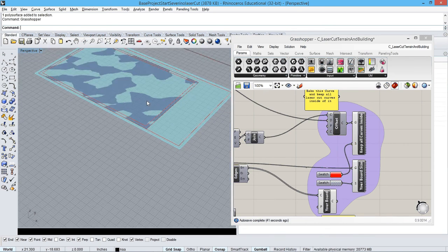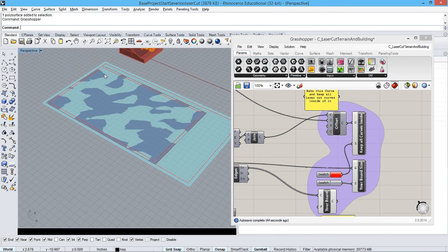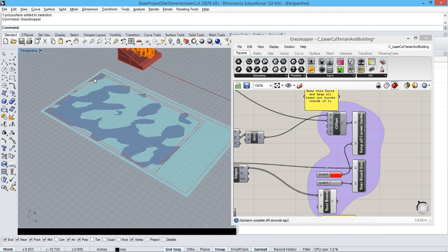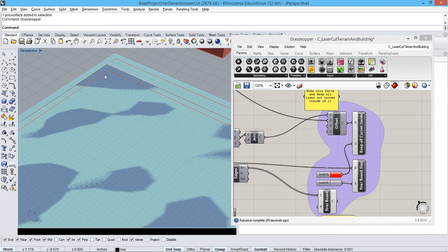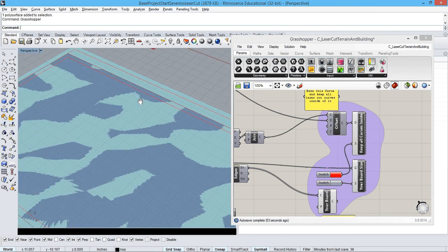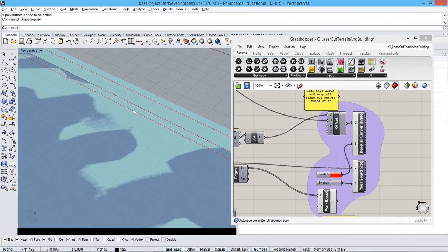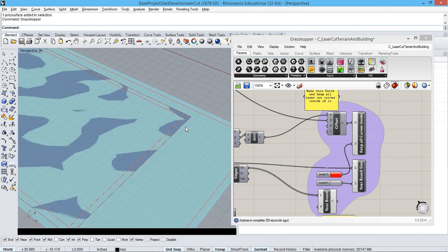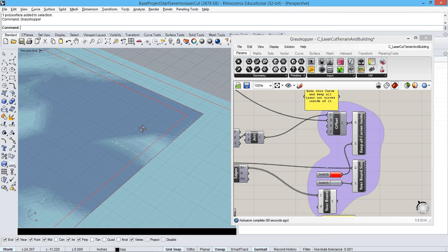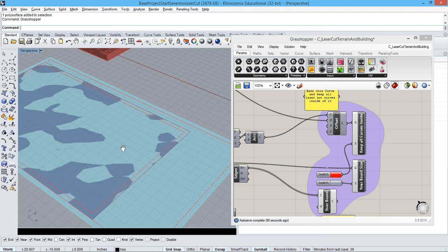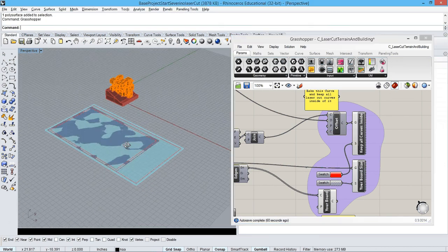We should put all the curves that we're going to create very soon in this video tutorial inside of the offset curve, so we make sure that we don't mess up the material border. That's the safe area. Never put polylines outside that curve, always inwards. We're going to bake that in a second.